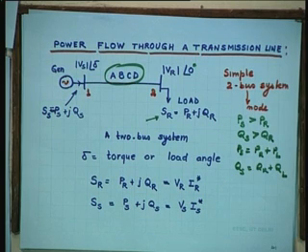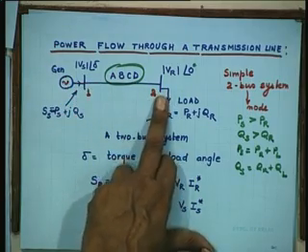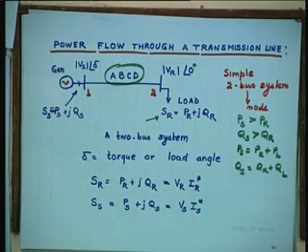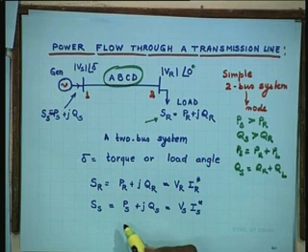But there is a possibility of QR greater than QS. No, not transmitted. That is because of load, that is because of compensation, not inherently because of transmission line. There is bound to be I squared x losses in the line. So, the reactive power which is generated here and pumped at this point, by the time it reaches here has to be less, unless until you have compensation along the route, then you are disturbing the system.